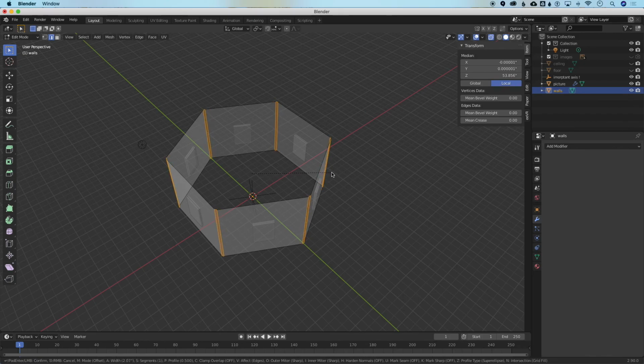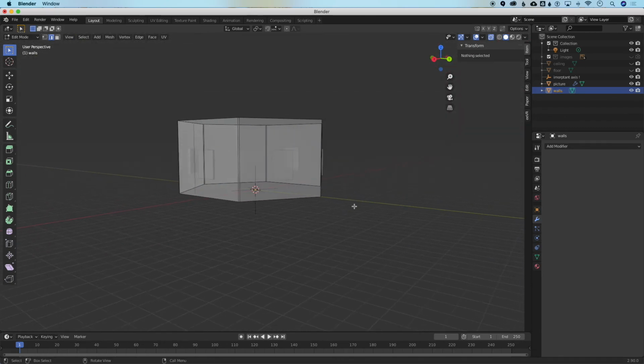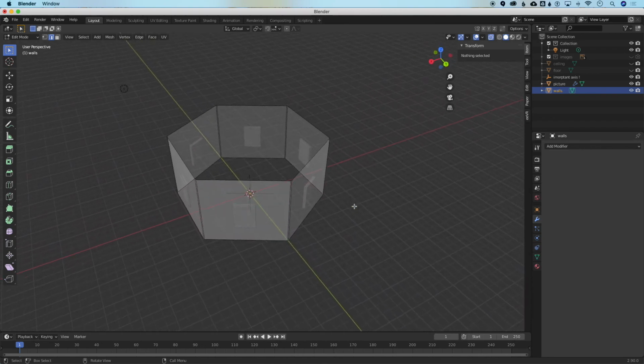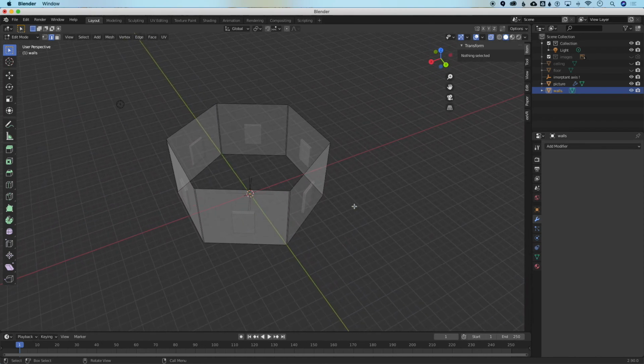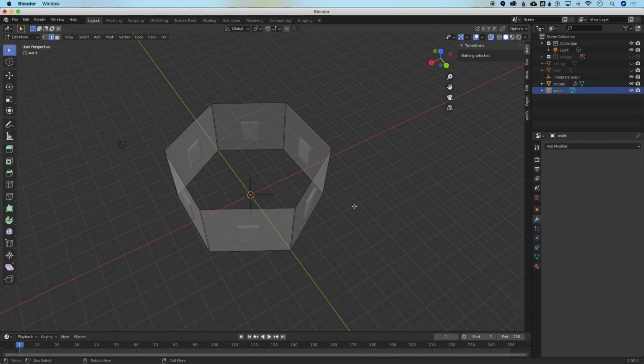If we have extra points here, you'll see all sorts of artifacts popping up. I'm going to put a tiny bit of bevel here because, as we discussed before, there aren't ever any true hard angles and things. I find walls look a little more natural if we put a little bevel inside them.